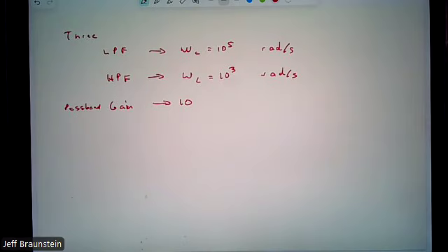You have two choices. We already discussed. It's either an RL circuit or an RC circuit. If it's an RL circuit, where's our output? Inductor. If it's an RC circuit, where's our output? Not the capacitor, the resistor. Sorry, I did that backwards. Low pass filter, RL or RC, we can do both. Low pass filter, output across the capacitor. RL circuit, output across the resistor.